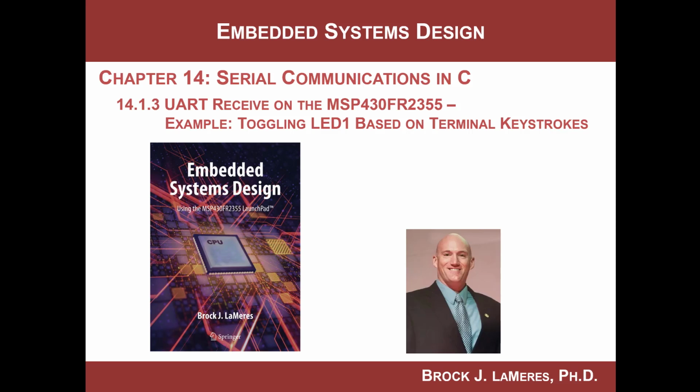We're continuing our study of embedded systems design. We're looking at the serial peripherals on the MSP430, specifically the UART receive. In this video, we're going to do our first example of using the UART receive. We are going to send ASCII characters from the computer terminal into the MSP430, and then we'll toggle an LED when we press T. When we press any other key, we'll see information come in, we just won't do anything.